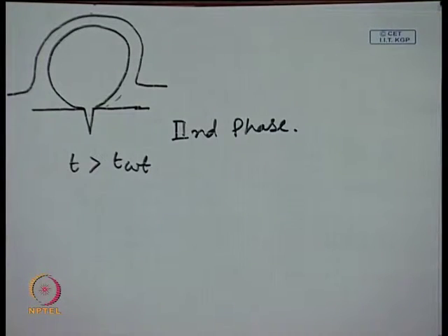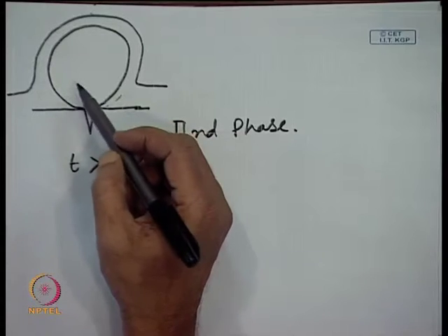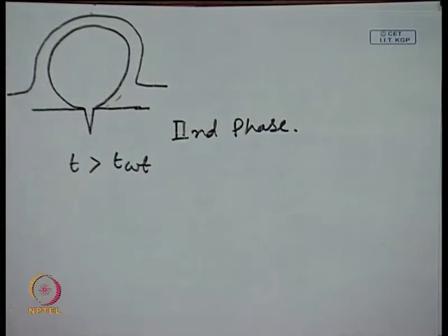Okay. And another thing you can see, I have represented the bubble as a spherical bubble. Why? Because now from the lower side heat transfer has really reduced. Now, more or less uniformly heat transfer is there all over the periphery. So, the bubble has become some sort of a spherical bubble. But one thing you have to remember, these are all ideal discussions based on some ideal model. In actual practice you will get something in between. Okay. So, this has become the spherical bubble.